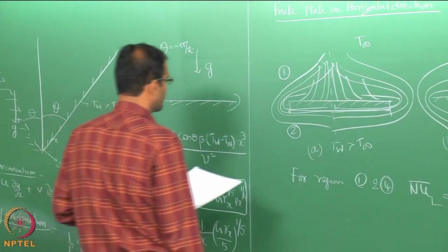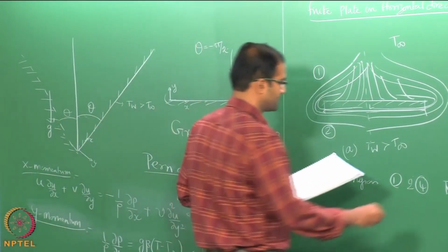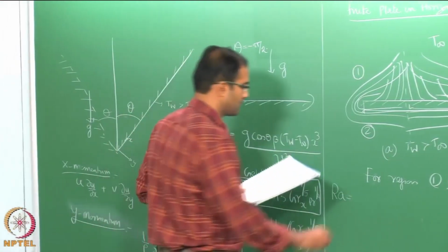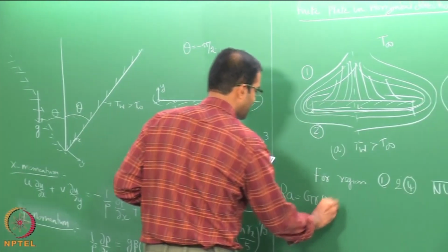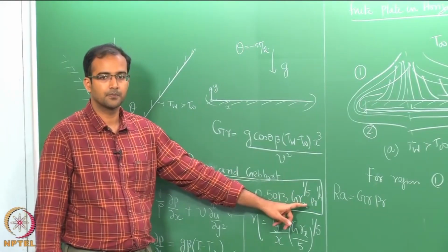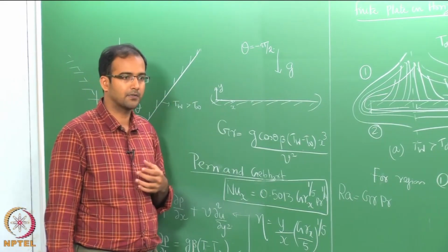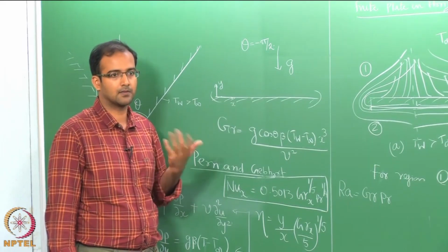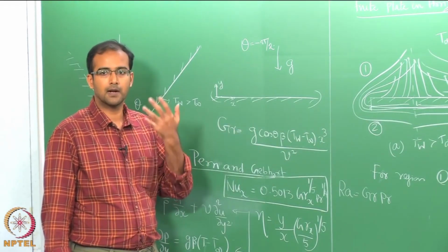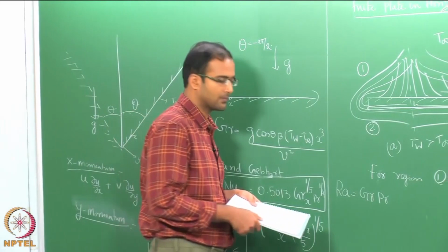Okay. So, so far we have not defined Rayleigh number, right? We have used everything in terms of Grashof number. So, we will define Rayleigh number. Now, Rayleigh number is nothing but another non-dimensional combination of Grashof number into Prandtl number. So, many times you see that Grashof number, Prandtl number come together. In some complex configurations the power of Grashof number and Prandtl number might be identical, such as this case. Okay, both Grashof number and Prandtl number raised to the power 1 by 4. So, in that case they can be grouped and you can have one single non-dimensional number called the Rayleigh number.